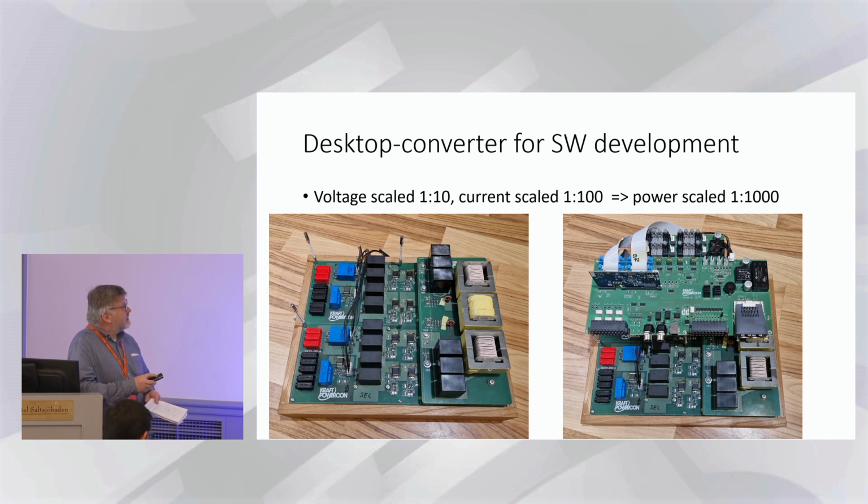The transformer is also scaled, and the commutation inductances and coupling capacitance. This is one power stage, and this is one power stage. On the bottom side here, we have the same gate drivers as we use in the big system, so it's exactly the same interface for the controller.